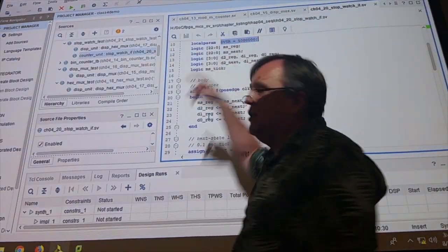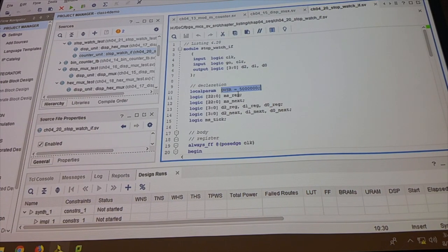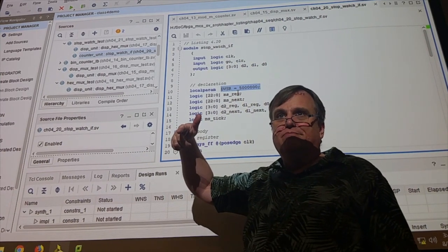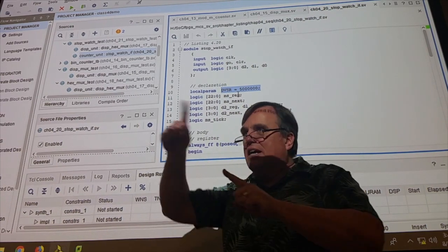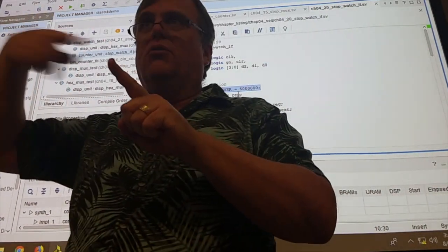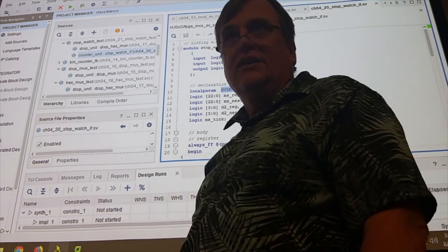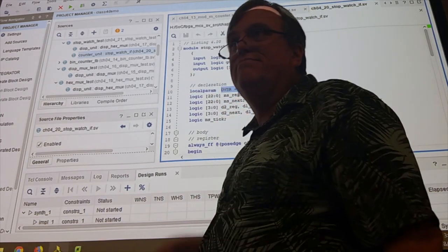So you can actually pretty much directly take this code, and just up above there was a start and a stop and a clear and all that kind of stuff. A go and a clear. So the go button will just be generated from your random circuit, right? So the second they hit start, it'll have a counter for that one that'll count to a random number, right? And then when it hits its limit, it will send that go flag, and then it's done. It moves on to the next state. And now you're just in here.